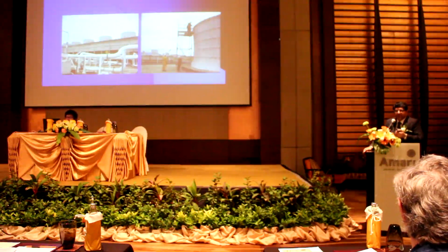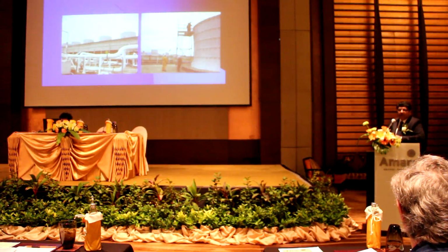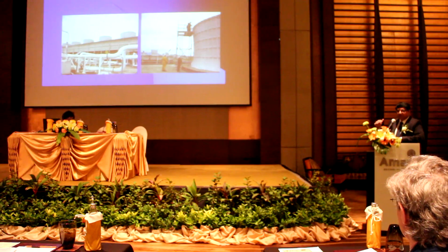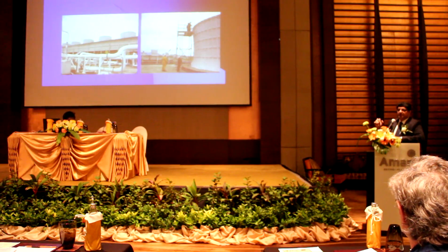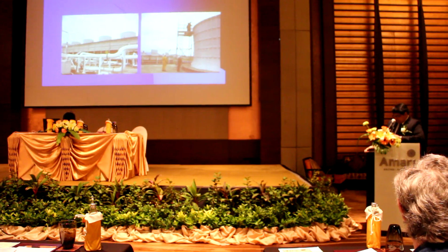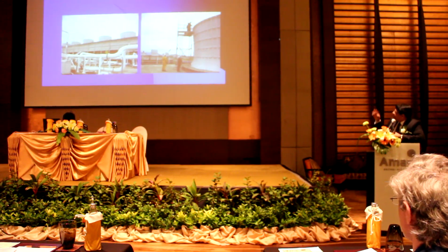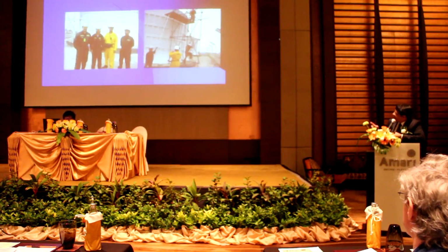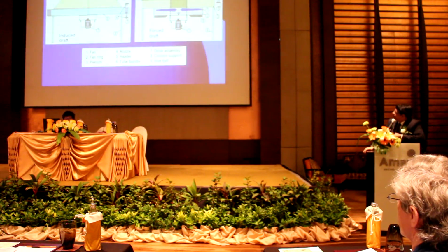There are engineering methods and procedures to find out by traversing anemometers on the exit of the fan in cooling towers, on the inlet of the fan in the forced draft air-fin coolers, or on the outlet of the fan on the induced draft air-fin coolers, or the air-cooled condensers that nowadays are being used for dry cooling systems. So this shows a little bit of the laborious work that is involved in trying to do the measurements for a particular installation.